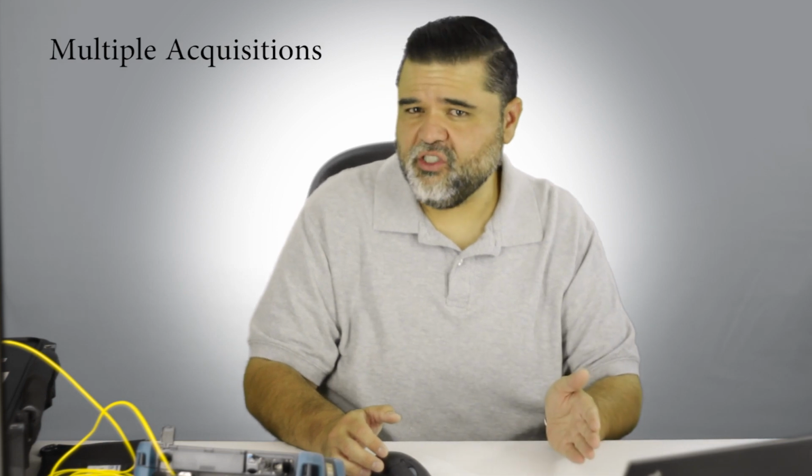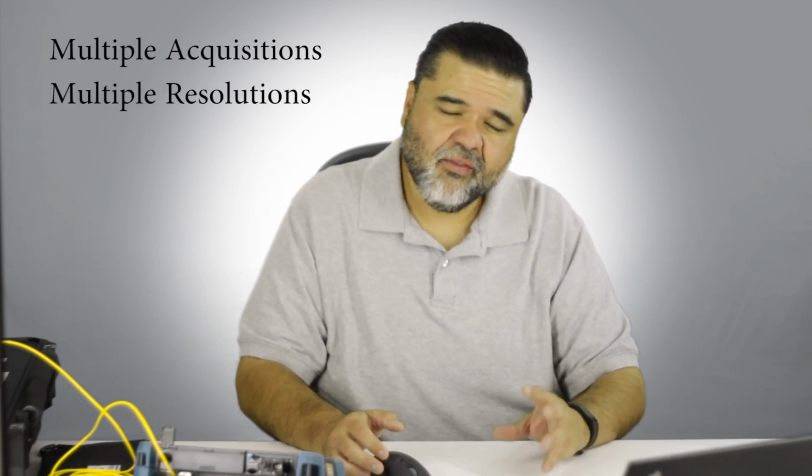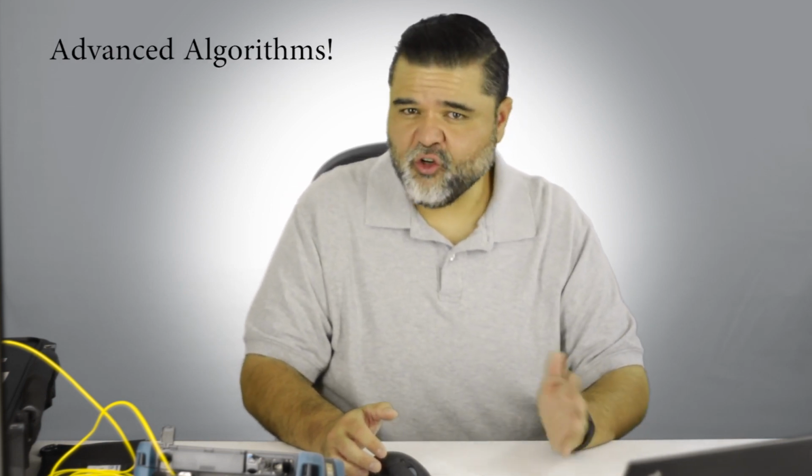So what is iOLM? Well, over the 30 years that EXFO has been in the industry, we've really been the leader in innovation of new technologies, and iOLM is one of those. It takes you beyond an OTDR, or optical time domain reflectometer. iOLM is an OTDR-based application. It does multiple acquisitions using multiple resolutions, then runs an algorithm on top of that and interprets the data.